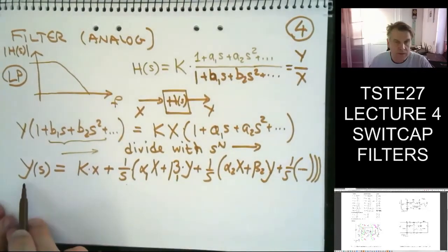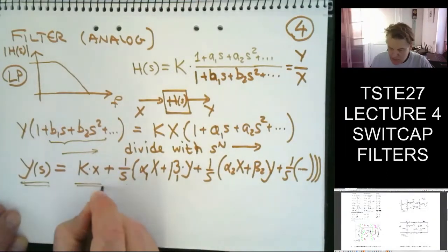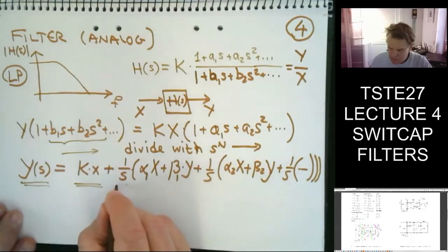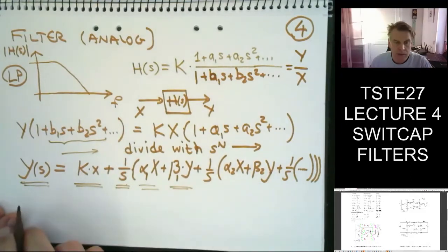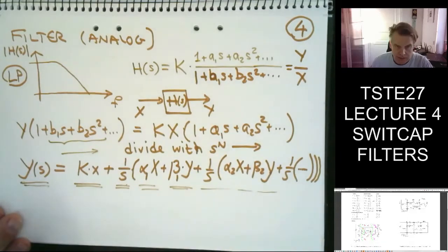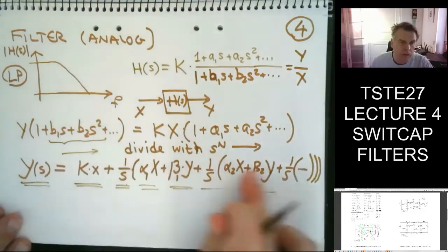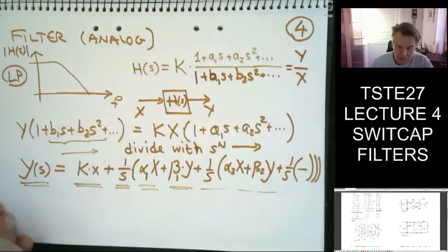So that means if you look at this, we can write the output signal as a linear combination of the input plus an integration of a feedback, and also a multiplication of the input signal plus further integrators. This is a typical normal form or transposed normal form that you may find in the textbooks in the basic courses.